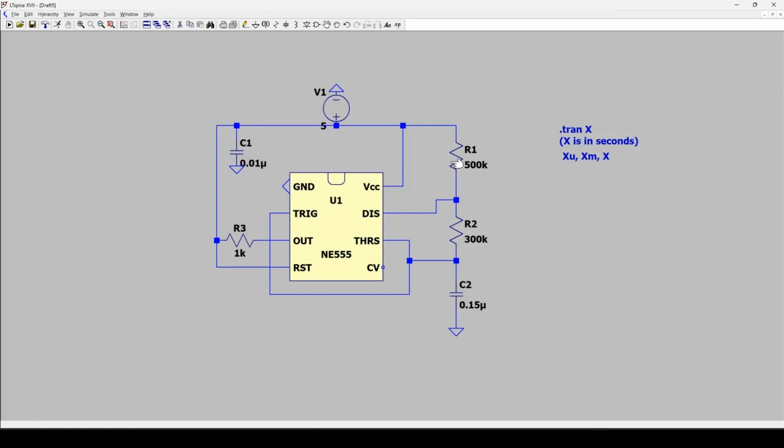So let's say you're viewing at a really fast frequency, like 1 megahertz. Running it at 1 second is going to give you, I would say, maybe not as clear-cut data as it would from a really, really low time frame, maybe even in the 1 microsecond range, excuse me. So something to keep in mind is that you need to choose the proper time range for your circuit.